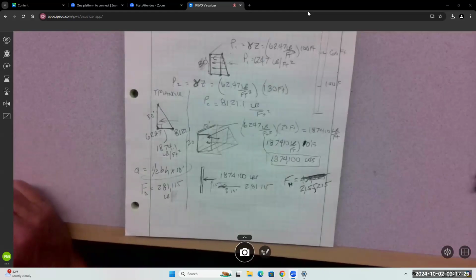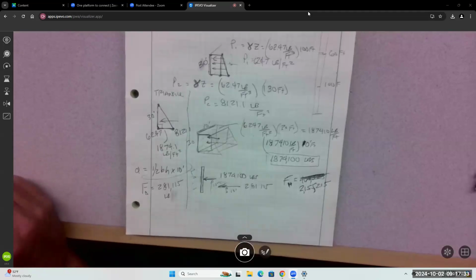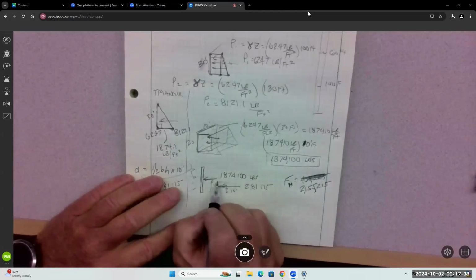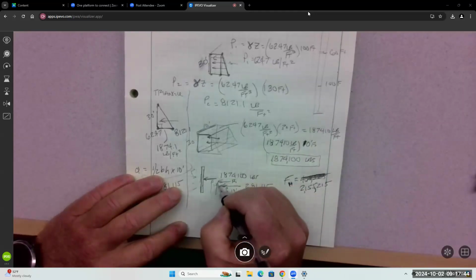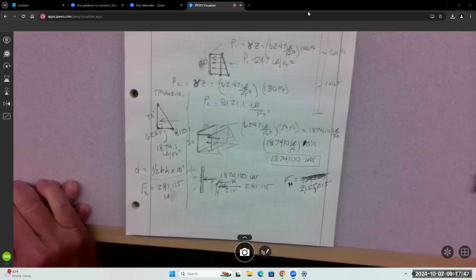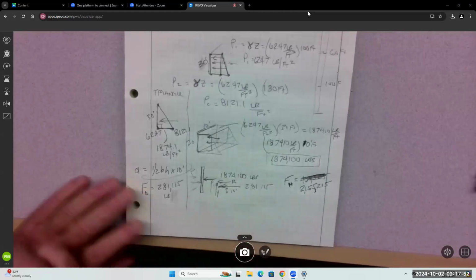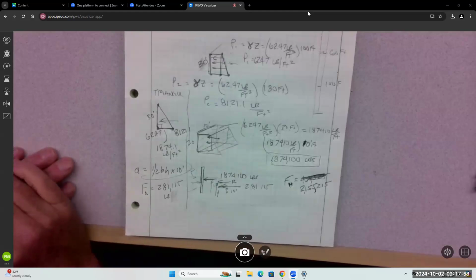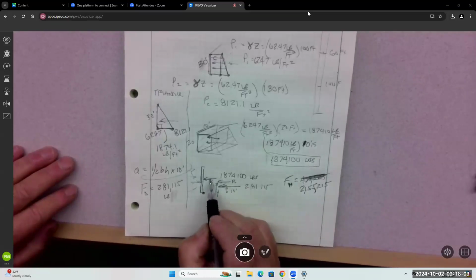Can we use our statics any way possible, thinking that this thing might be in equilibrium? In other words, there's something holding this thing in place over here, right? You could treat it like a beam and do the beam stuff. So we could say the resultant is here, I'll call it R at some Y distance. But everything's gotta be in equilibrium, so let's push the equal opposite resultant away. We should be able to just calculate moments. This one's creating a moment about this point.